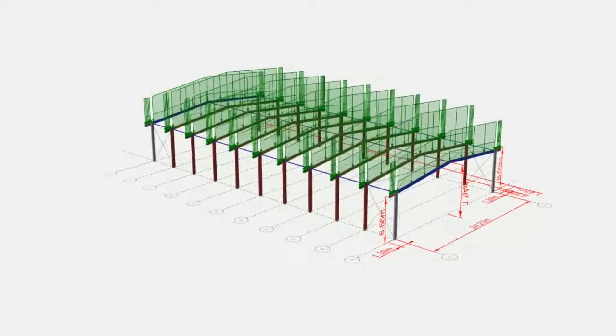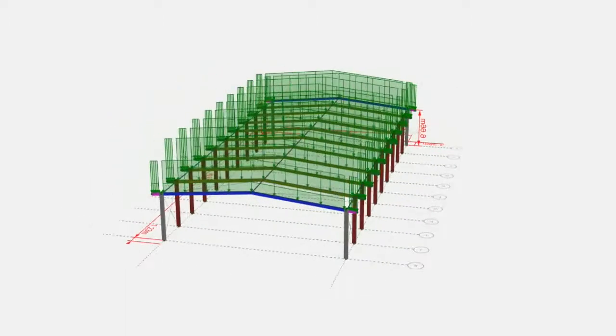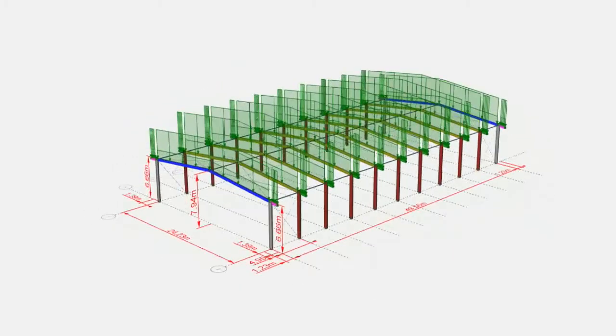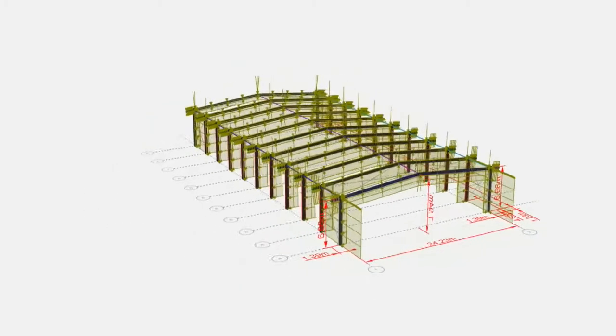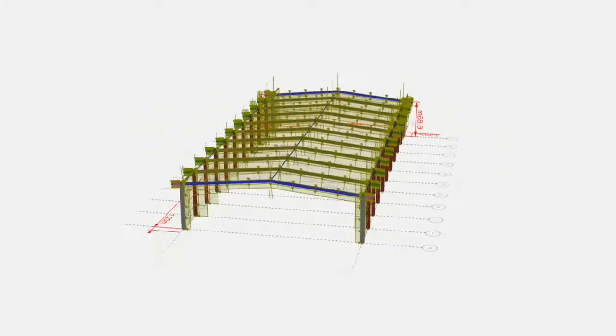Vertical loads are transferred through the roofing into the purlins. The loads then travel along the purlins into the rafters. The load travels through the rafter, down into the wall, and along the wall into the bracing. The lateral loads go straight into the wall, through the cladding, and down into the bracing.